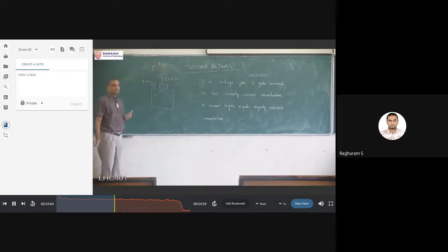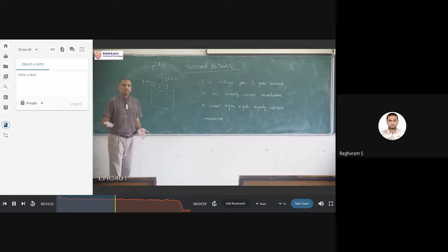This is one equation, and in this equation N is the number of charge carriers, or the number of particles carrying the charge, and that is 400. Now 400, maybe when I was growing up 400 rupees was a big number, but today everything starts at 500 rupees only. You can't do much with 400, but still in terms of this equation, this Q is 1.6 into 10 power minus 19. So when that gets multiplied with 400, your current is going to be in 10 power minus 15 amperes. 10 power minus 15 amperes is very low.